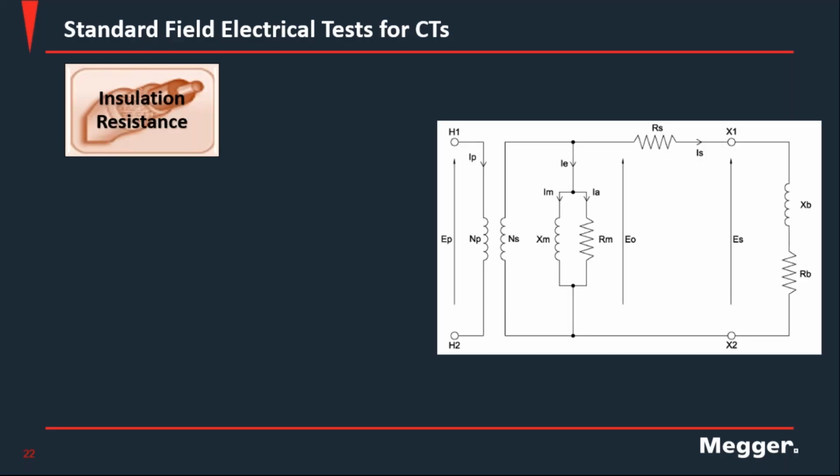Let's talk about the different test activities that you perform. Of course, with any electrical equipment, the very first test you want to run is insulation. And you want to assess the insulation. In this particular case, I'm showing insulation resistance. But depending on the type of CT or VT, the voltage level, the current level, you may have oil insulation, or paper, cellulose immersed insulation.